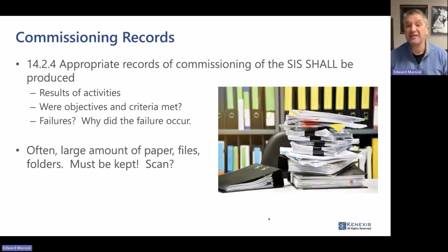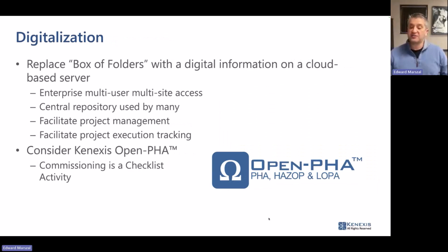Okay, well, that is the state of the art. It does meet the requirements of the standard. And I would say for most of the functional safety assessments and audits that I've been involved in myself, that's generally what I see. I see a PDF of the loop folder. So there'll be literally a folder for a loop with all the scanned documents that were the result of that loop. Okay. So that is the state of the art. That's how we do things now, but we can do better.